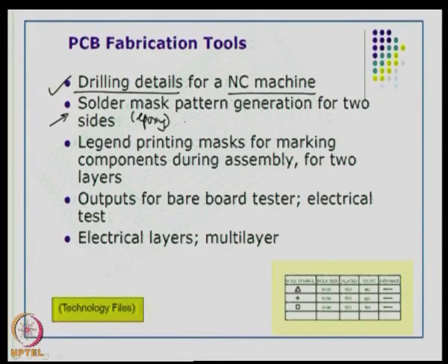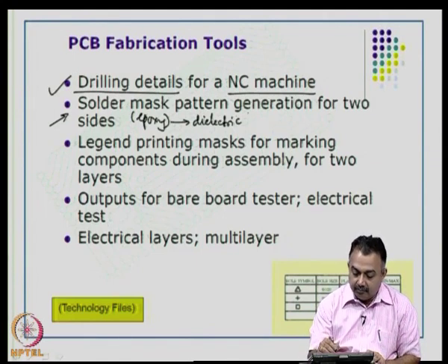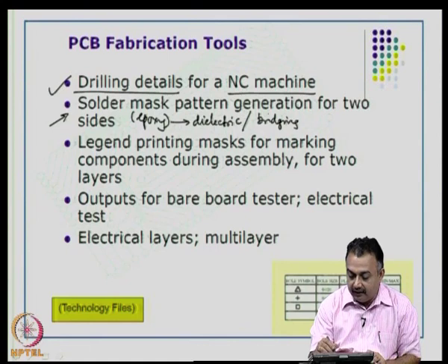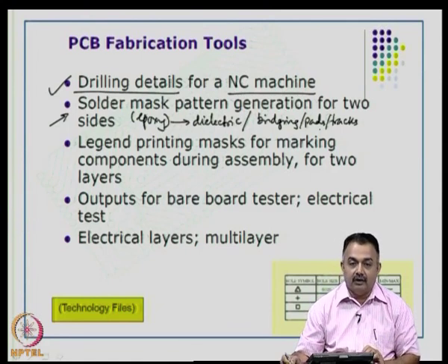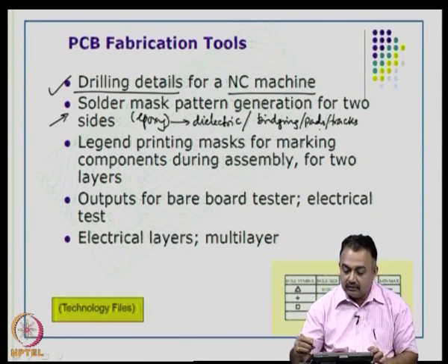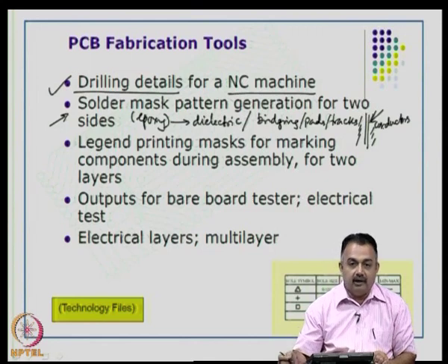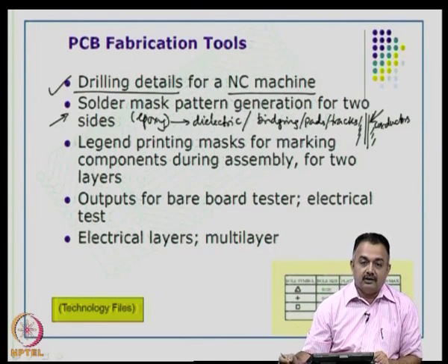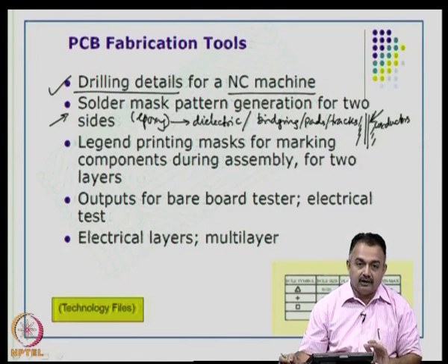What does it do? The solder mask here, it is an epoxy, therefore, it is a dielectric material, right. So, what is the function of a dielectric material? It protects all your conductor areas, it takes care of bridging of any pad or let us say your tracks, and it takes care of providing better electrical performance like elimination of crosstalk, noise and so on between two close conductors. So, if you imagine two conductors here, then imagine there is solder mask in between these conductors and the outside areas. Obviously, it provides a better electrical performance. And imagine in a high density circuit, these lines will be very close, and also the pads will be very close to each other. A pad will be very close to a via structure and so on.